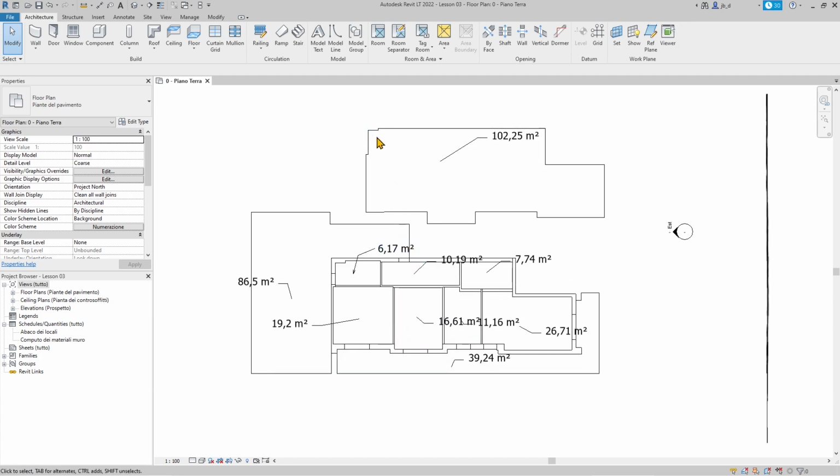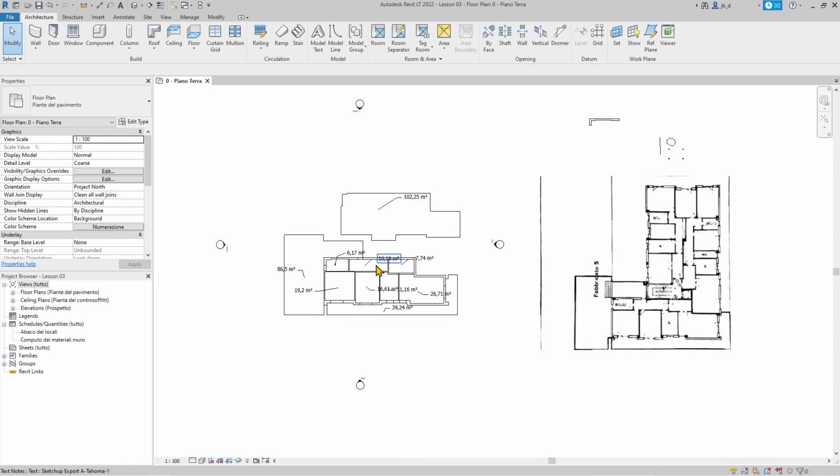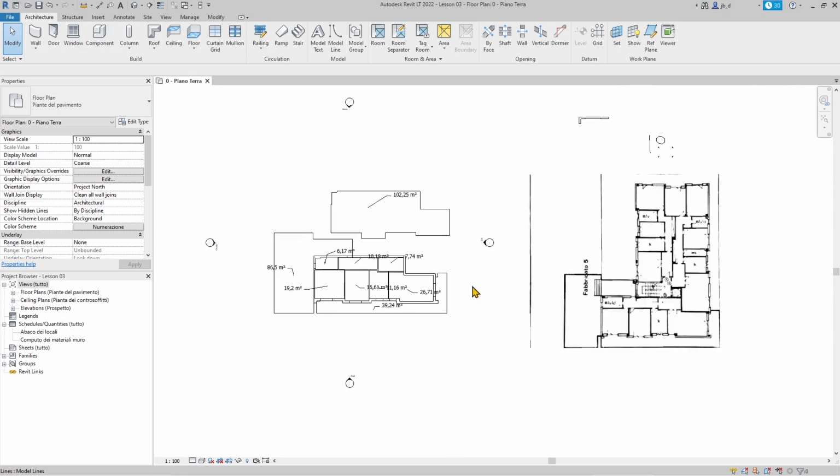You can also create only the perimeter like this, and then create the walls here with the thickness in Revit. And again, we're going to see that later. I will first start with importing assets different from families, and then we will see the families in the last part of the video. So first of all, we can import like that by just clicking, dragging, and dropping inside Revit.